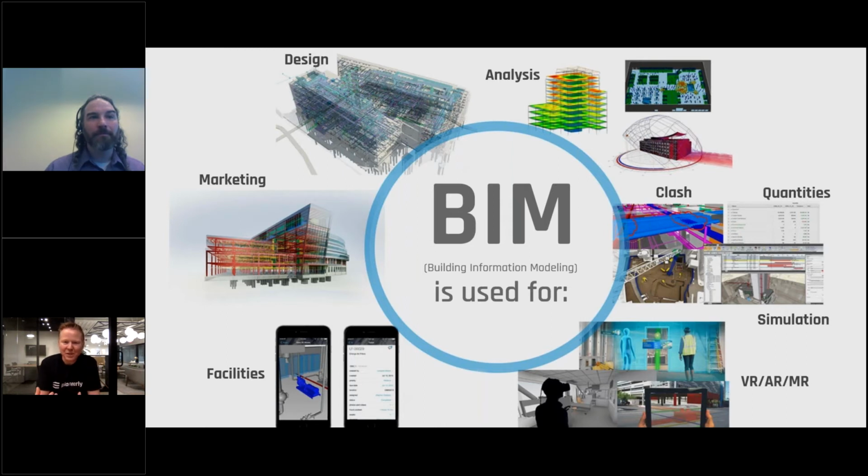And the model that you take quantities from is going to be completely different from the model that you use in facilities potentially. It depends on what you're using the model for as to how and what you put in, when it goes in, how accurate is required, etc. So there's this complex set of use cases for BIM, and being able to identify what those are before you go and create a model that's not going to be useful for one of those is really, really important.